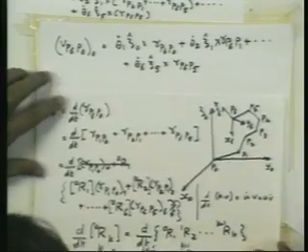Okay. So finally, the velocity of this turns out to be physically very easy to obtain. All you need to do is, one by one, move a joint keeping all the others fixed. The velocity that you get out of that is the linear velocity that you get for the point. Now this is true whether the joint is revolute or prismatic. It holds, and it can be shown that it holds.